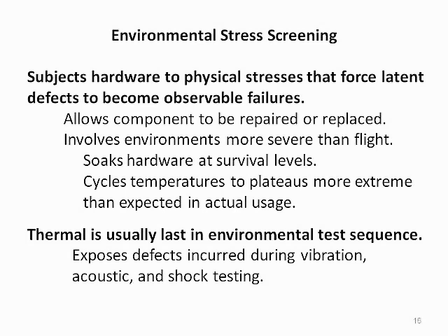Environmental stress screening subjects the hardware to physical stresses that force latent defects to become observable failures. This allows components to be repaired or replaced prior to usage in flight. Stress is introduced by subjecting the article under test to environments that are more severe than what is expected in flight. This is accomplished by soaking the hardware at extreme survival temperature levels and cycling temperatures to plateaus that are hotter and colder than expected in flight operation.